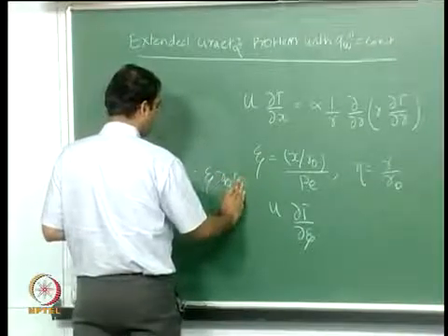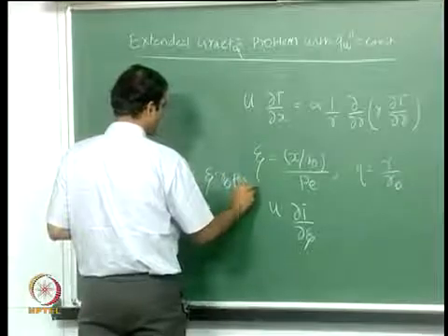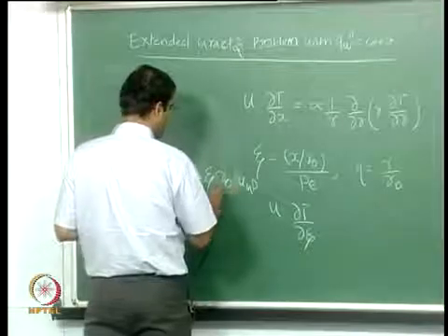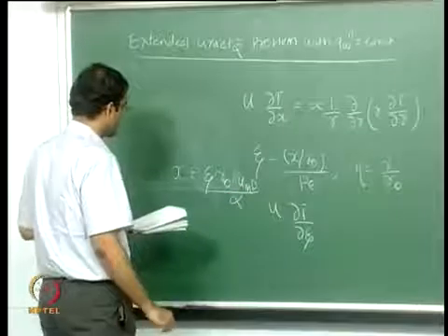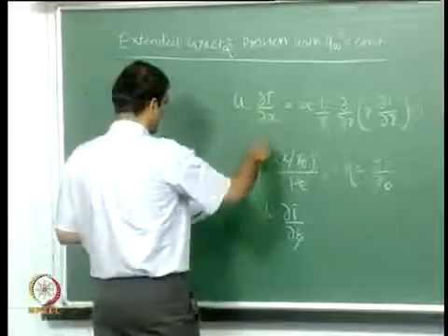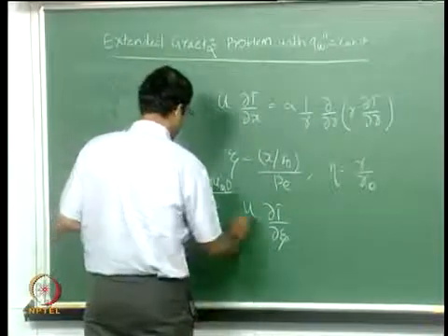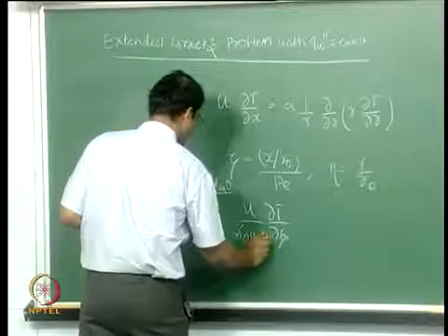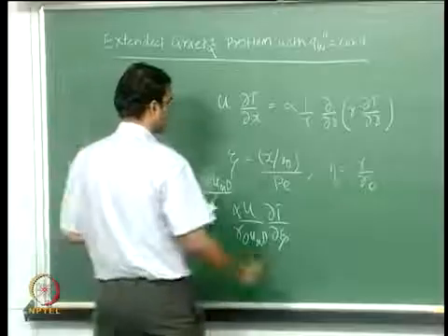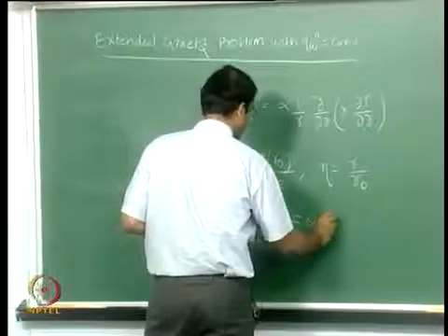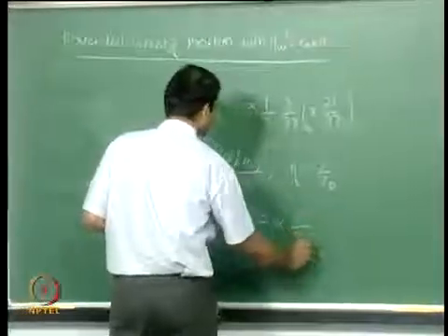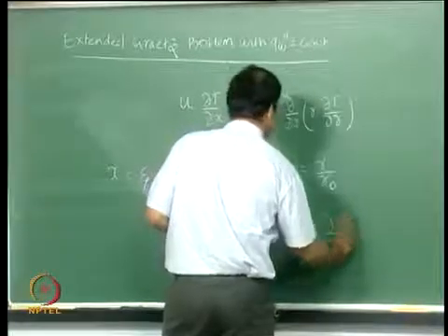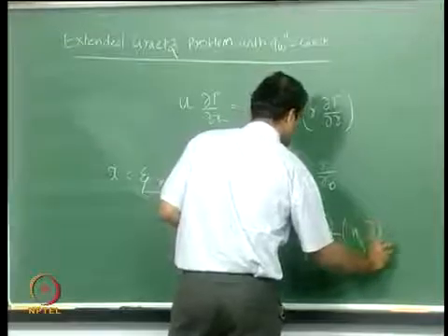number. Now the Peclet number is nothing but rho um d by, or you can say um d by alpha. So this I can substitute in place of x, so this becomes r naught um d, and the alpha goes to the numerator here, so this is equal to alpha 1 by eta d/d eta of eta dT/d eta.